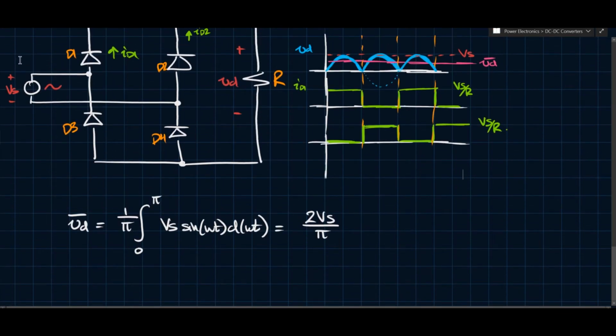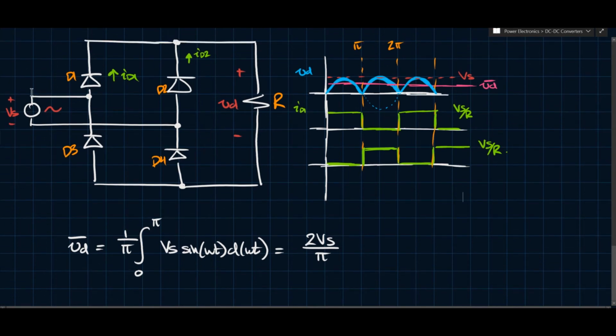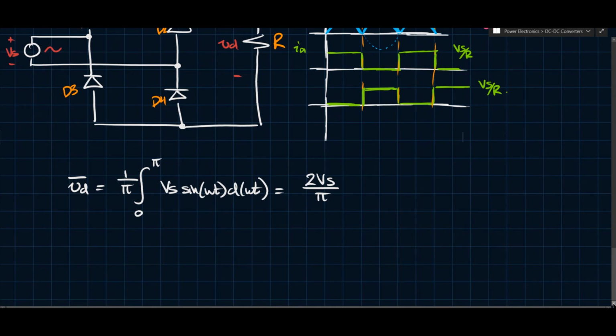So if this is a 120 volt mains connection, let's say, you might step it down by a factor of 10 so that it's a 12 volt signal here. A 12 volt voltage is much easier for diodes to be rated for than 120 volts, for instance, and then you can deal with everything afterwards. So this is the standard sort of bridge rectifier case.